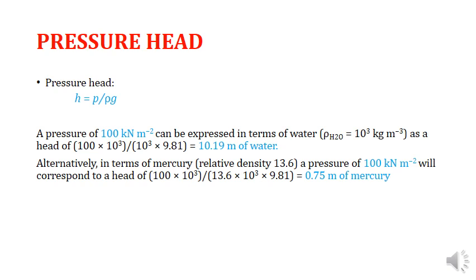So what is going to be the dependent factor now? The dependent factor will be the density. To develop the same pressure for different fluids, if the density is different for the different types of fluids, then the pressure head developed for this particular type of fluid will be different. Okay, so this is the conclusion that we have made till now and we are discussing.